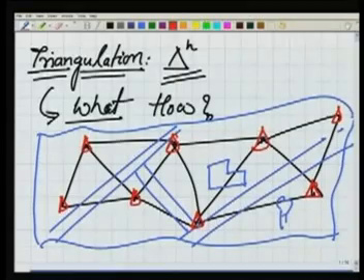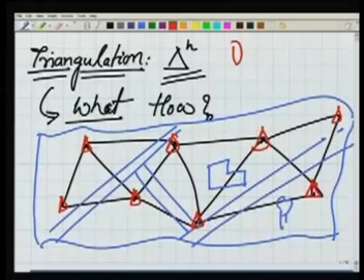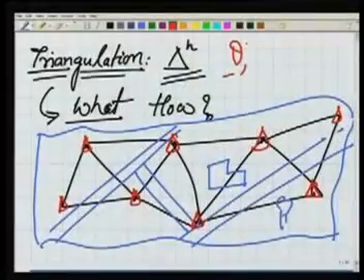Well, why the triangulation is important, why it is significant? If you remember, in those days when the EDMIs were not available, now also even if the EDMI is available, we have to measure so many distances in order to make the triangles by measuring the lengths. So at that time when the length measurement is costly, because EDMI is a costly instrument, what we would like to do, we would like to make use of our theodolite, which can give us very cheaply the theta, the angle measurement. So in this figure, if we have an instrument which can measure the angles, the theodolite, very cheaply and without much cost,